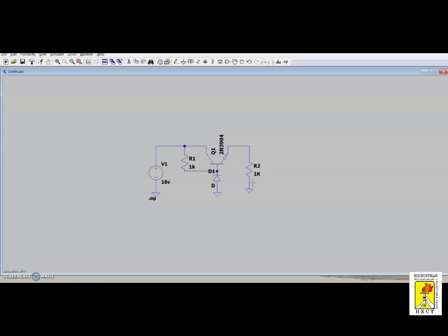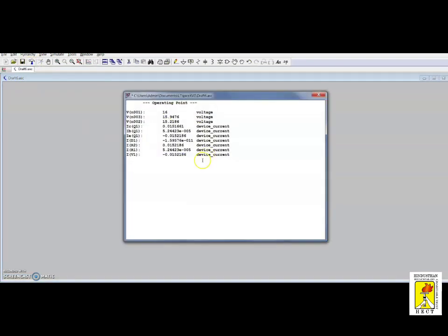The one thing we have to note here is load regulation; I am going to show an example of how to show the load regulation. In line regulation, we have to fix RL as a constant 1 kilo ohm, change the input voltage, and measure the output voltage. So let us see the line regulation simulation first. Go to run.